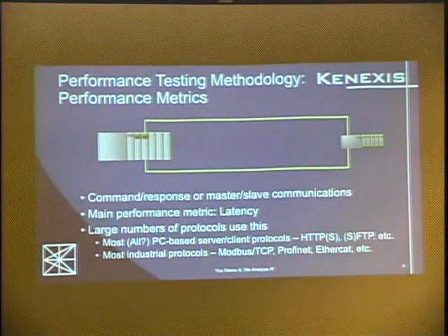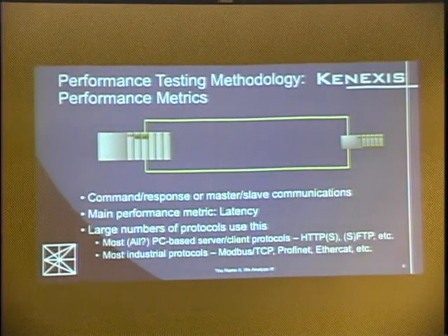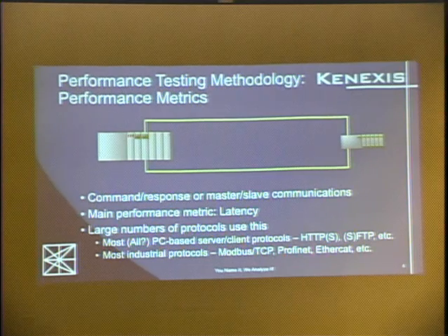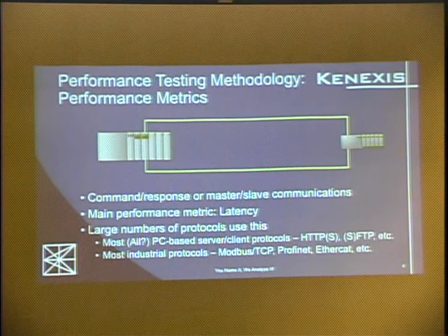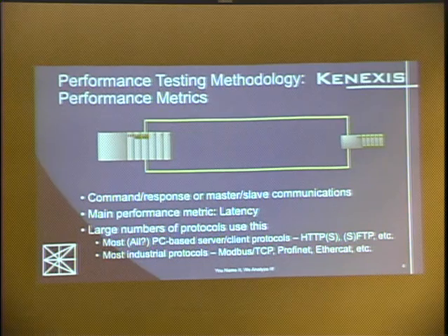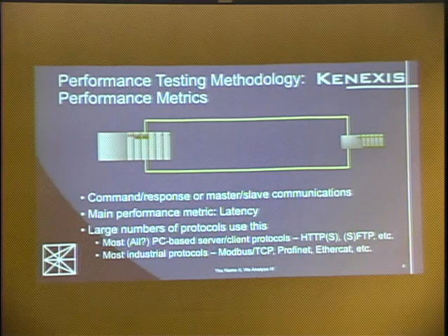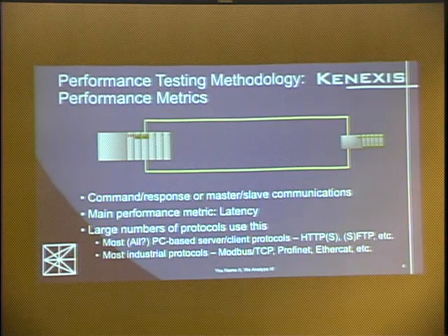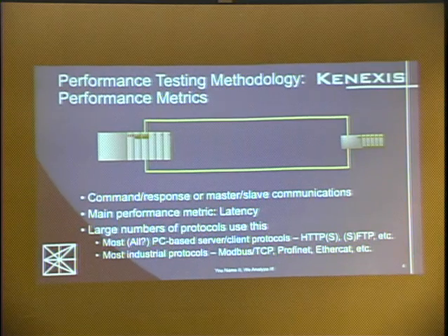The other mode that you typically run in is command response. This is for a lot more of the protocols. A lot of the standard IT protocols run this way, client-server kind of stuff. And a lot of the other industrial protocols that may be older or more specialized run a command response system as well. In this case, you want to make sure that the command that you sent is responded to as quickly as possible. You don't want the slave device sitting there chewing away on that for a long period of time and then sending you back a response with a lot of delay. So that latency is really important.